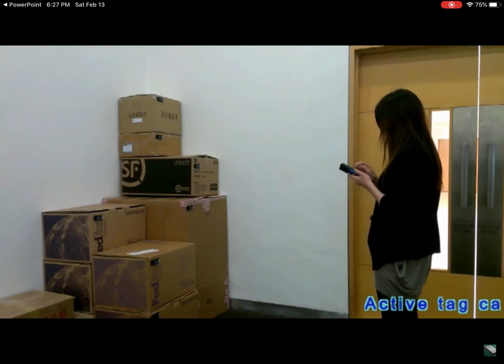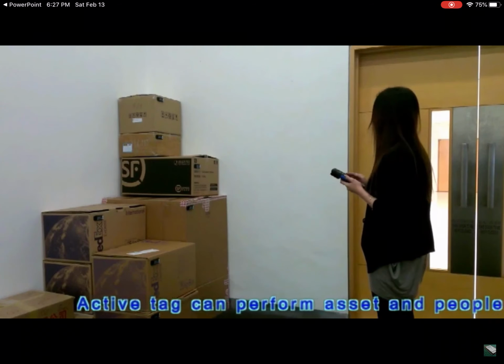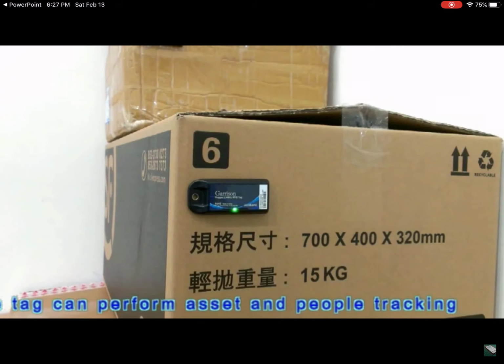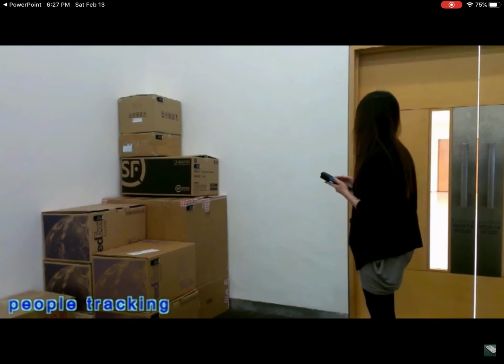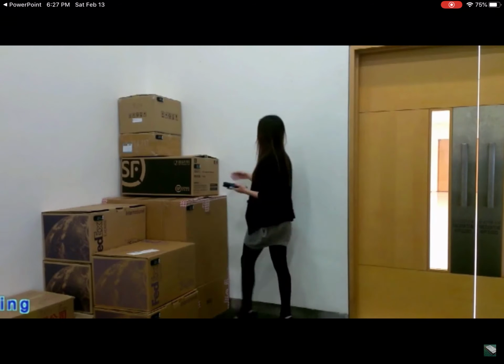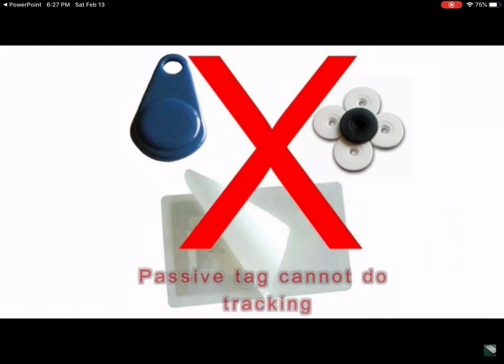With battery inside, active tags can achieve a much longer reading distance. By constantly sending the tag ID to the reader, active tags can facilitate different tracking applications. For passive tags, which do not have a power source inside, no tracking applications can be achieved, as the reading distance is shorter and the tag can only be read when someone taps it against the reader.